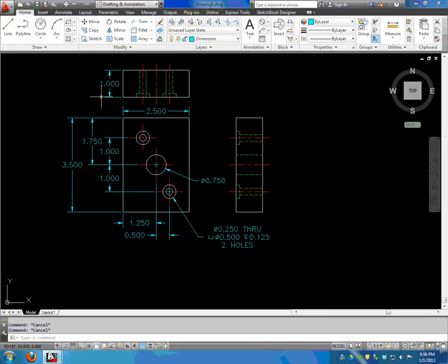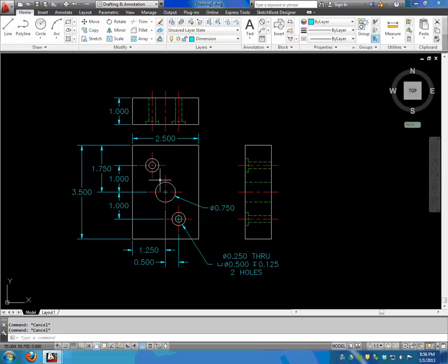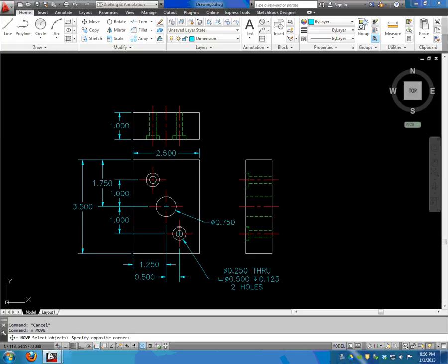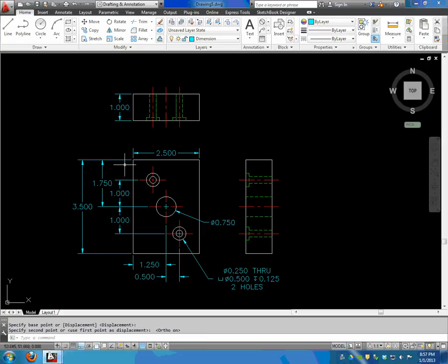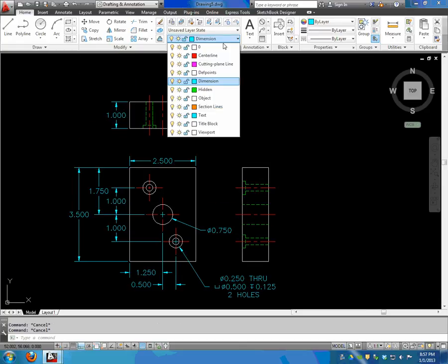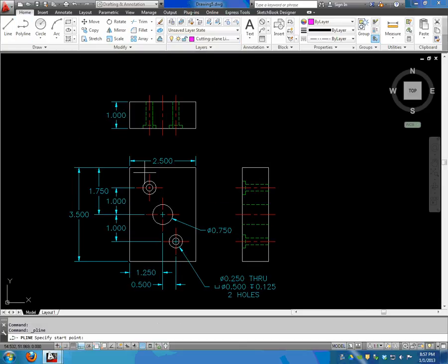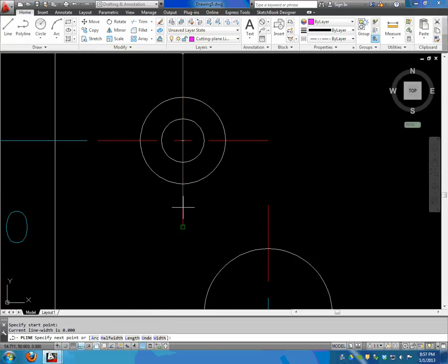So now the fun part of showing our section view, which is going to probably have to tweak my dimensions some. So we're going to go ahead and take, I'm going to pull this up, turn my ortho on, pull it up some, and that dimension is going to have to change a little. So let's go cutting plane line. I like using polylines for this, just for the fact that it stays consistent. So we'll just go ahead.